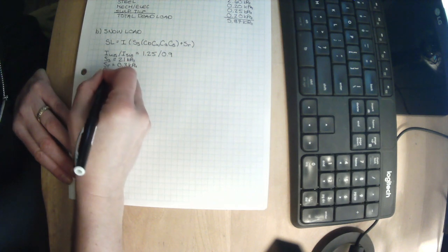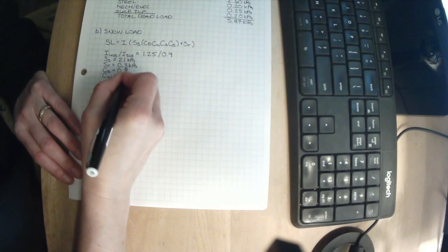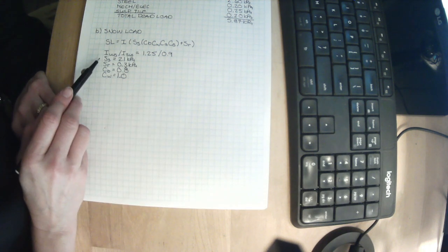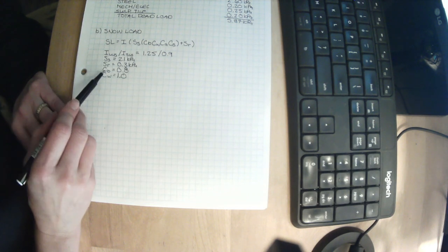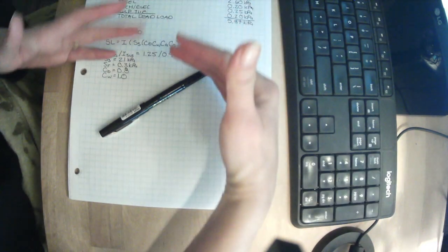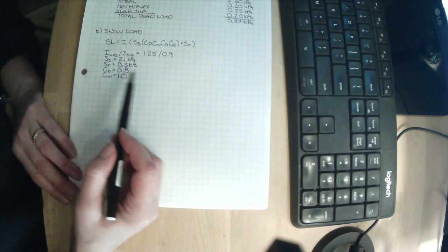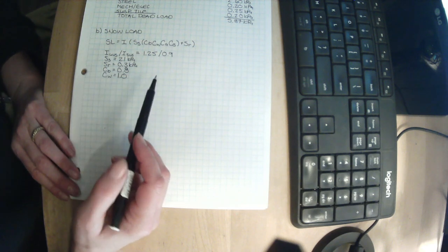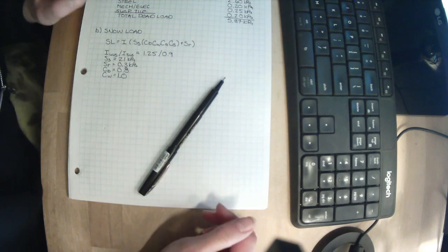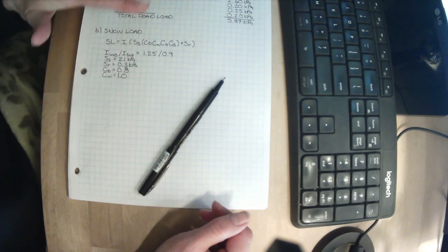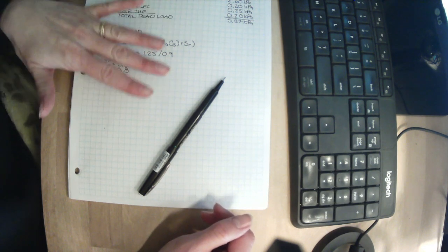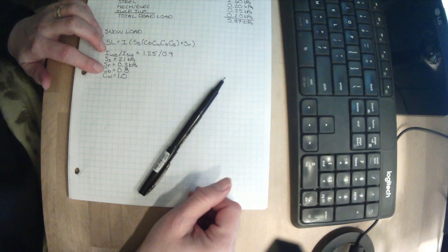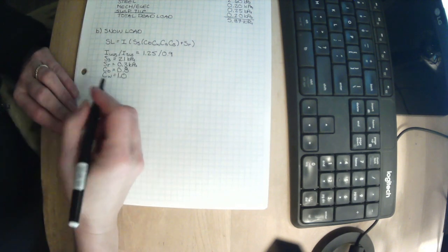Oh, we forgot CB. If you guys remember, CB is just the factor that we apply because we're talking about a roof rather than the ground. The loads they've given us here are the ground snow loads. CB means that it's up on the roof. At least a certain amount as it falls down comes off of the roof. If you have a gigantic roof, like a warehouse or something like that, CB can start to equal 1, but usually only in the interior of the building. So I've done some very large community centers that were 1 story and they had 2 rinks and 2 swimming pools. So it was a gigantic roof plan, and some internal portion of that roof had a CB of 1. But for you guys, you're not going to worry about it. It's going to be 1.